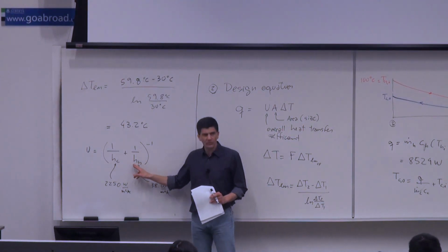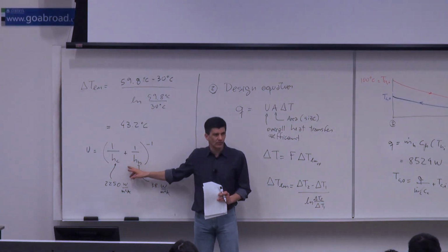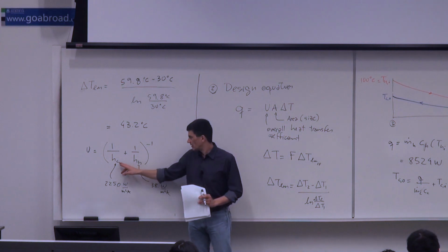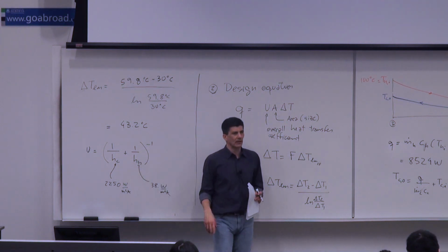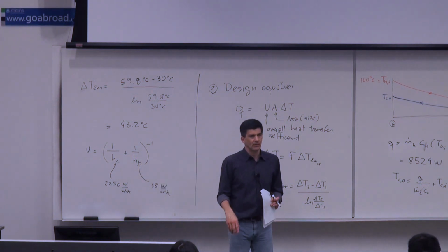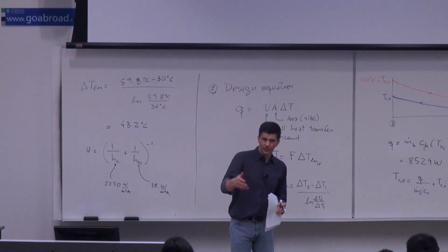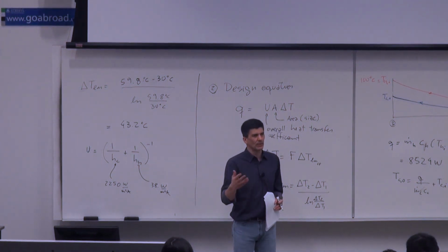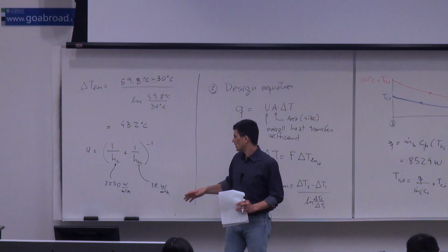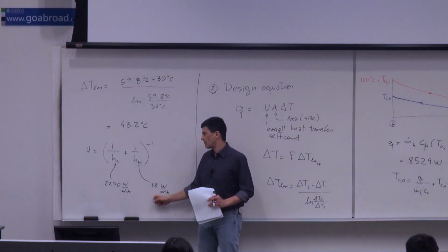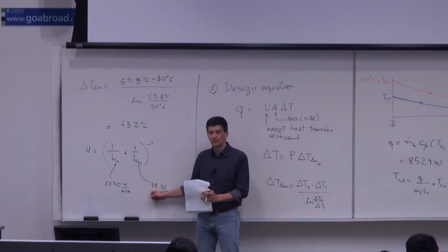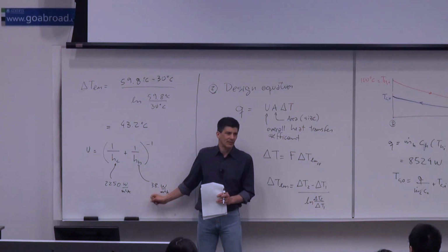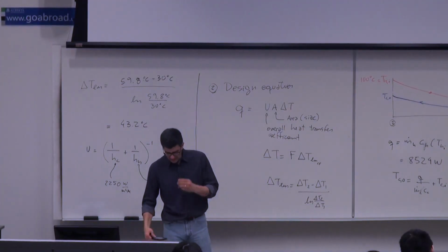These calculations, when you go to the book and you see, both are internal flow calculations. And they're quite difficult. You have to check for the Reynolds number to see if it is turbulent or not, right? So what you're going to see is that this is turbulent and this is laminar. So maybe you can try to make this one turbulent, right? Things like those. Let's calculate the length of this heat exchanger.